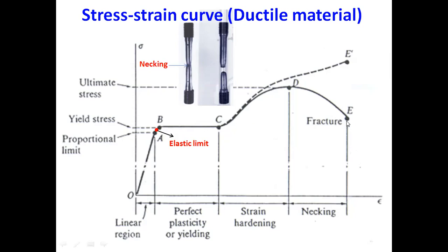From here to here, this is just a theoretical line. In order to make it closer to reality, normally you will take the vernier caliper, pick the failed specimen, and measure the diameter at the neck. Then you have to enter the new diameter, which would be less than the old diameter.